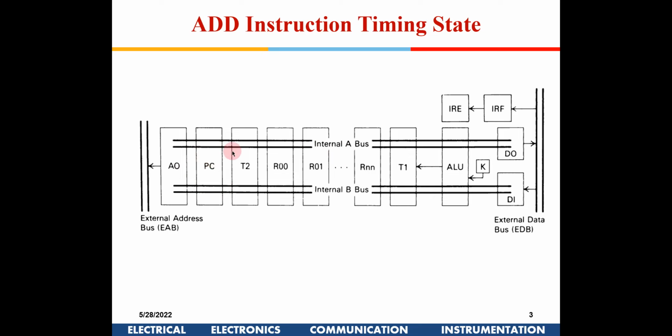It is not that PC and ALU will be connected in one go. In phase 1, PC will be connected to the internal bus. In phase 2, you don't do anything, you allow the data to stabilize in the internal bus A, and the switch which connects this data to the ALU will be powered only in phase 3.